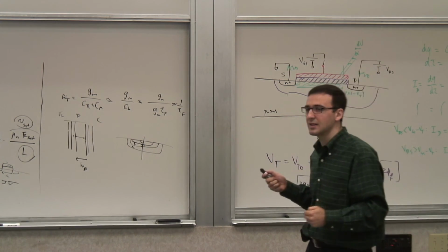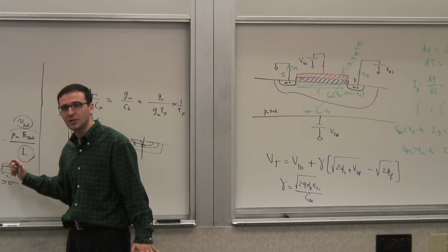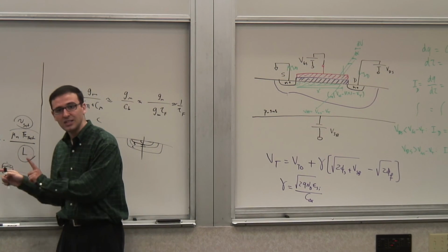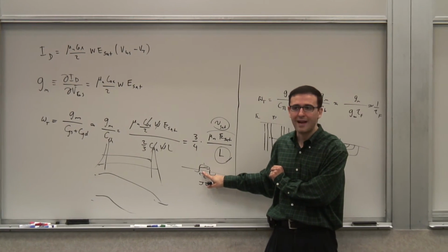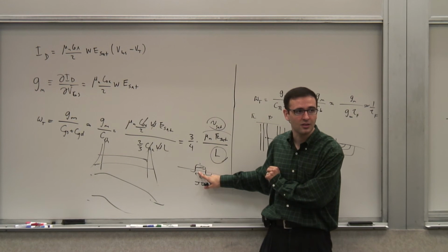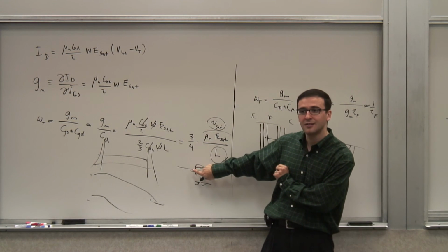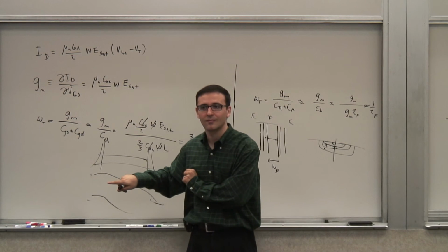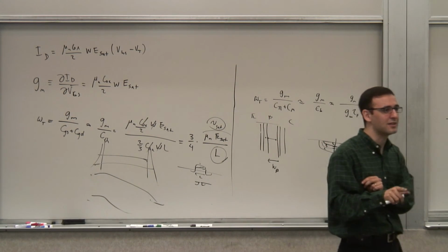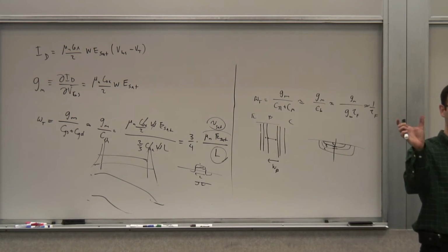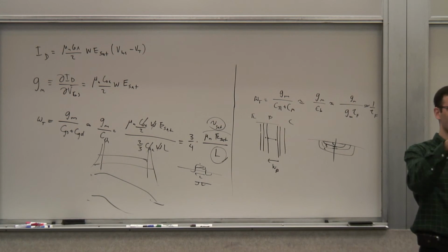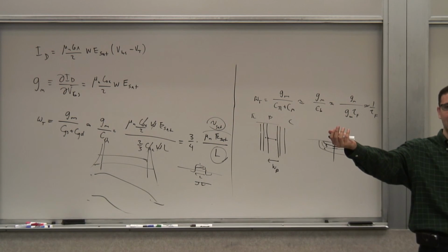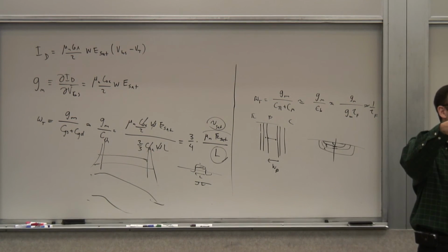The good thing about a MOSFET is that no matter how much you overdrive it, if you want to turn it off, you just lower this voltage. And these charge carriers have a place to go. They don't have to disappear through recombination. They can go back to the drain or source, which cannot happen in a bipolar transistor. Right? Because drain and source are n-type regions, n+ regions. There's plenty of room there for these extra electrons. If you want to turn it off, the electrons go back. If you want to turn it on, they come back in. They pour in from the n+ regions.